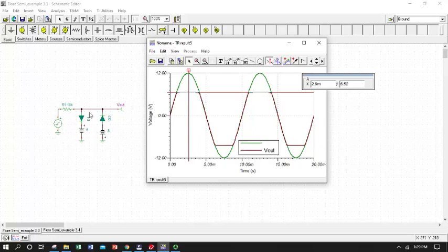See if we have that correct on our forward. We have 6. So we have a potential of 6 here. So we'll have to supply a voltage. Ooh, excuse me, math in my head. My voltage at this node is going to have to be the forward bias, which is about 0.7, plus 6, so 6.7, which my test told me. So my clip plus the forward bias voltage, so that's 6 plus, not 6 minus. Very good. This is a good reason to run tests.